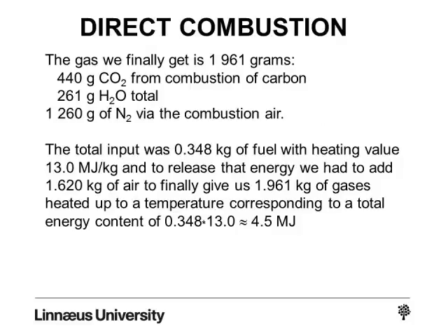The total input in this case was 0.348 kilos of fuel, and that fuel had a heating value of 13.0 megajoules per kilo. To release that energy, we had to add 1.62 kilos of air, and that gave us finally 1.96 kilos of gases.